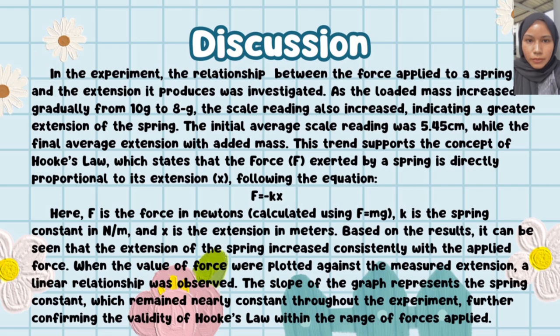So by plotting the force against the measured extension, we observe a linear relationship. The slope of this graph gives us the spring constant, which remained nearly constant throughout, confirming Hooke's law was valid within our test range.